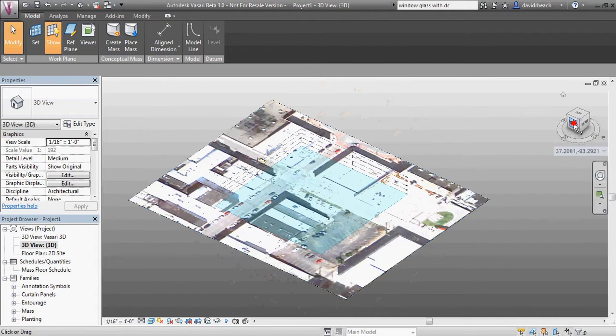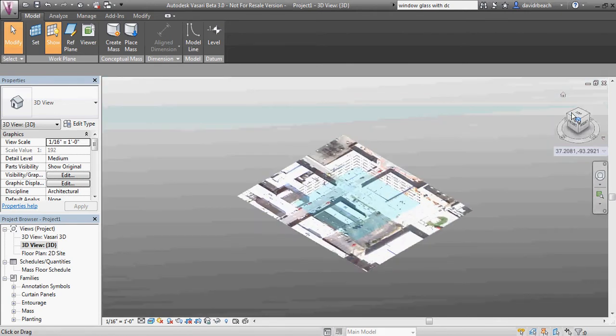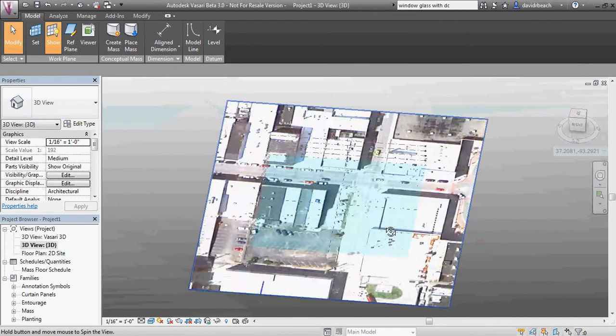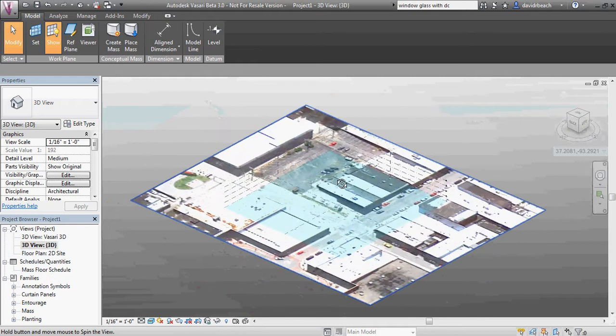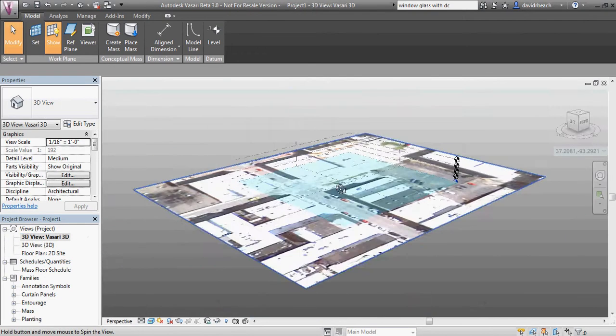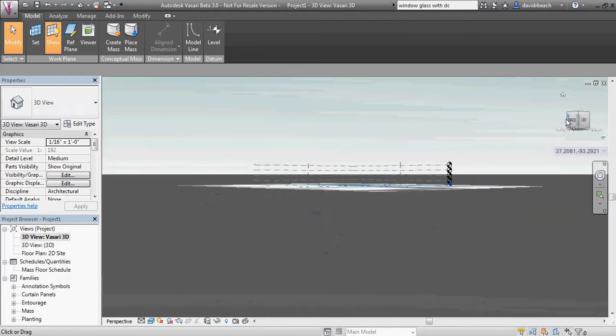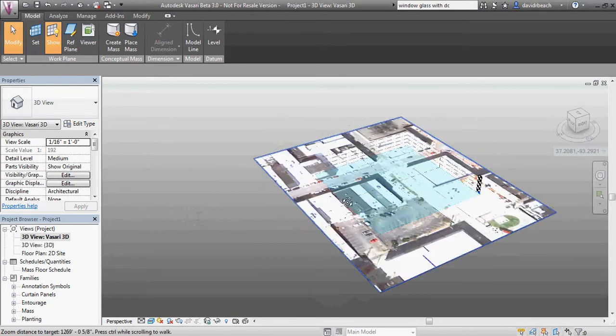I can also use the view cube to go to elevation views. So again, I'm in my axonometric view, or a sideways-on axonometric view that I can orbit around. Or if I'm in my 3D view, I can do some of the same types of things, but remember these views are not true elevation views because I'm actually in a perspective viewport looking at it from this direction.